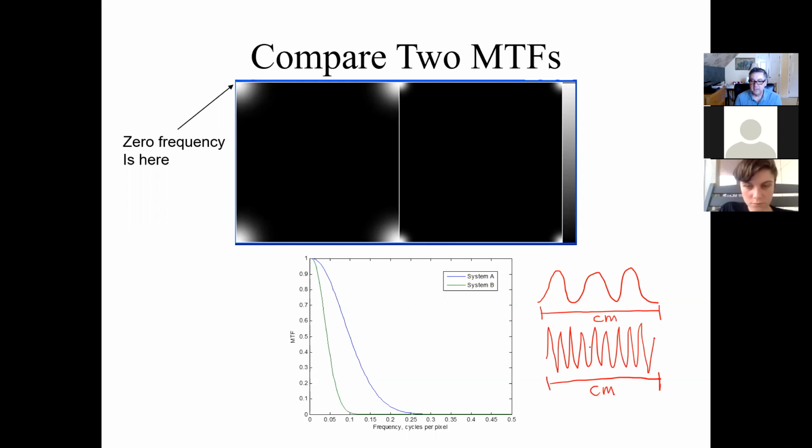The higher frequency has more details, of course, and therefore is able to express things to a better resolution, in the way we usually think of spatial resolution. Or another way of looking at it, right, is that if I want to express something with a lot of detail, then it's going to have some components of high frequency in it. Okay, if my system is not responsive to high frequency stuff, then it's going to limit the amount of detail I'm going to be able to have in the output.